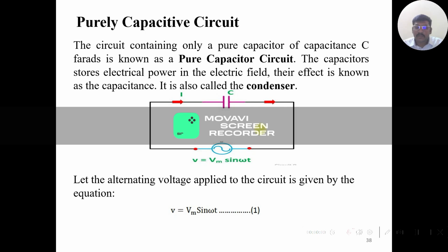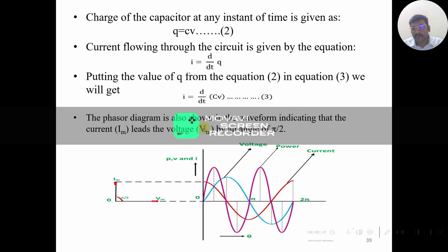So today we are going to see about the simulation of capacitive load. Here a capacitive load, or capacitance, is connected in parallel with the AC source. This capacitor will withdraw a current which leads the voltage by 90 degrees. This is theoretically proven, and we are going to check this with the simulated model.